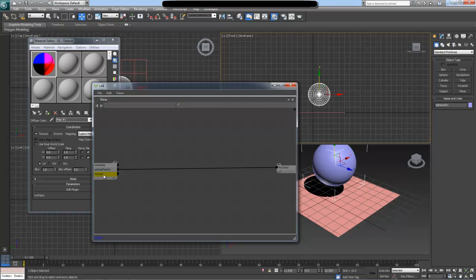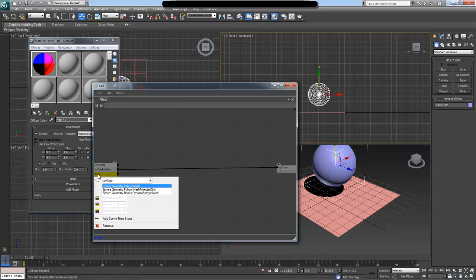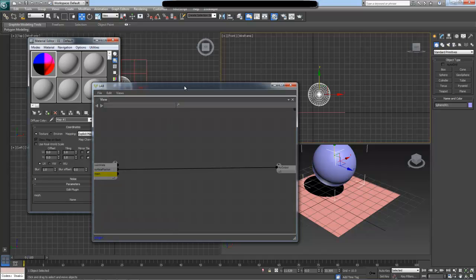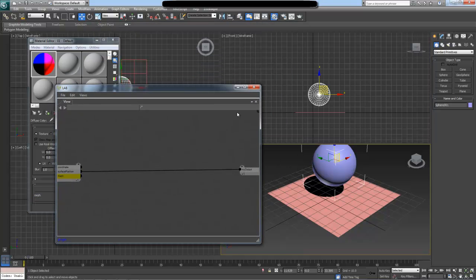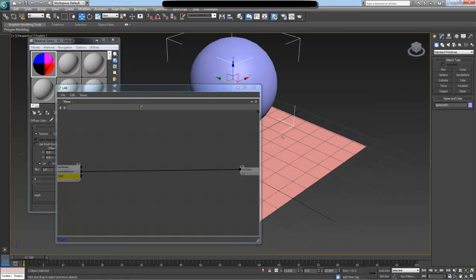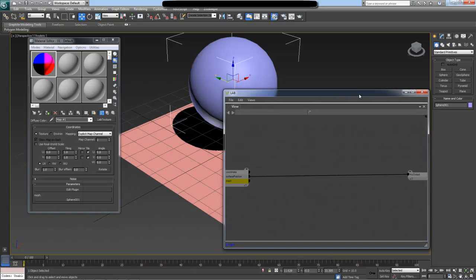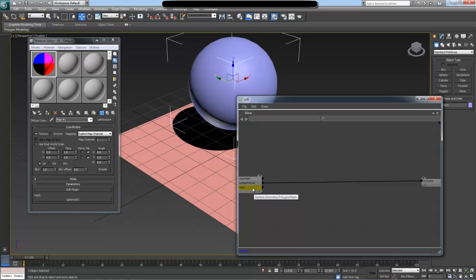Let me rename my input to a mesh input, and I'm going to change its type to polygon mesh so that we can accept the sphere as one of the inputs. And I'm just going to select the sphere, so don't forget to do this later on. Along with the sphere, we will also need to take the sphere's world coordinate transform, because all of the points inside the sphere mesh are currently in object coordinates, and we need to get a way of getting these points to appear in the same coordinate system as our surface position.